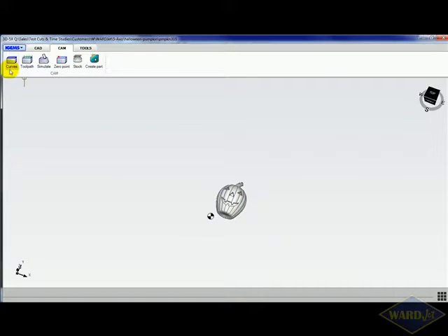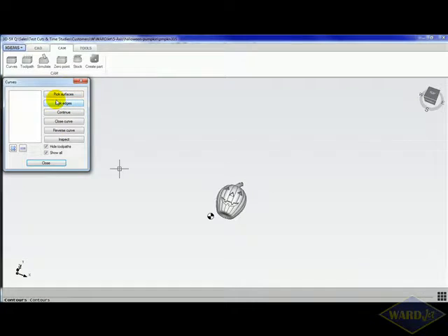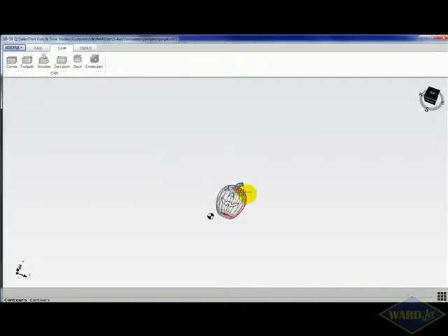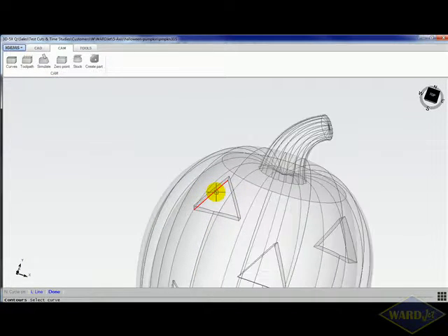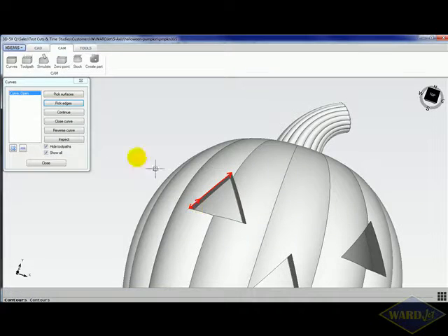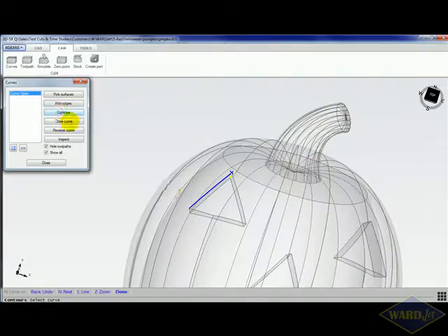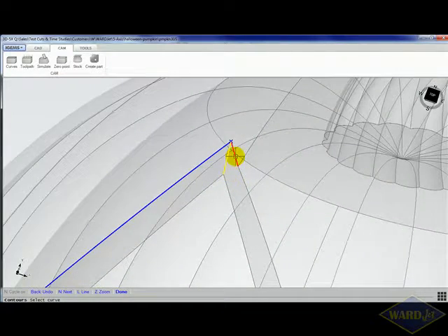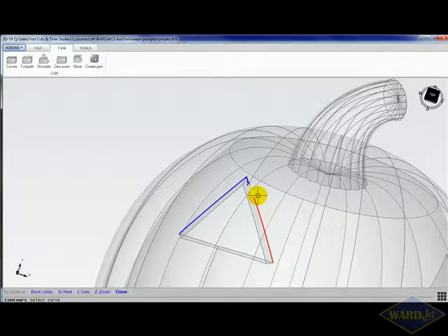Let's see, if you go into the curves area, of course, still the options for picking surfaces, picking edges. If you are picking edges and you get part way through it, then decide that you want to go back and continue, or you just miss a line, there's the continue option now. So if it's an open curve, you can click on continue and then come back in and select and continue on with picking edges and such.